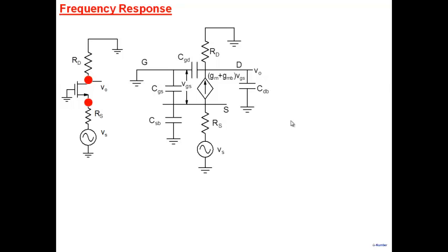If you look at this particular circuit, what you note is that I have to include now the source to body capacitance here. Source is here, and remember body will be connected to the most negative point, which is ground here. So body is connected to ground while source is no longer at ground. Normally source to body capacitance was not coming into picture for common source, but for common gate, I have to put a source to body capacitance here. And CGS, of course, is over here.